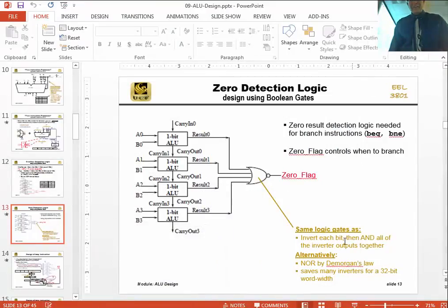Well, I've subtracted A and B, and then what am I going to do? This is checking for 0, but there's actually, remember the most significant bit? This is represented as bits, right? If the most significant bit is a 1, I know it's a negative number right off the bat. Suppose the most significant bit of the subtraction is a 0. Well, it could either be equal or greater. I need more information to determine which of the two.